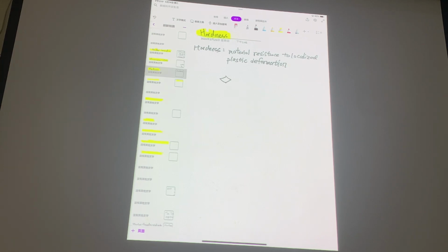Now, for those that do ceramic materials, oftentimes when you do the Vickers hardness, you get this dimple, right? And you might ask, hey, professor, how about we do 100 gram? Usually it's measured like this. They don't give a gram. They just say 0.1 means 100 gram, 0.5 meaning 500 gram, and HV1 is 1 kg, right?